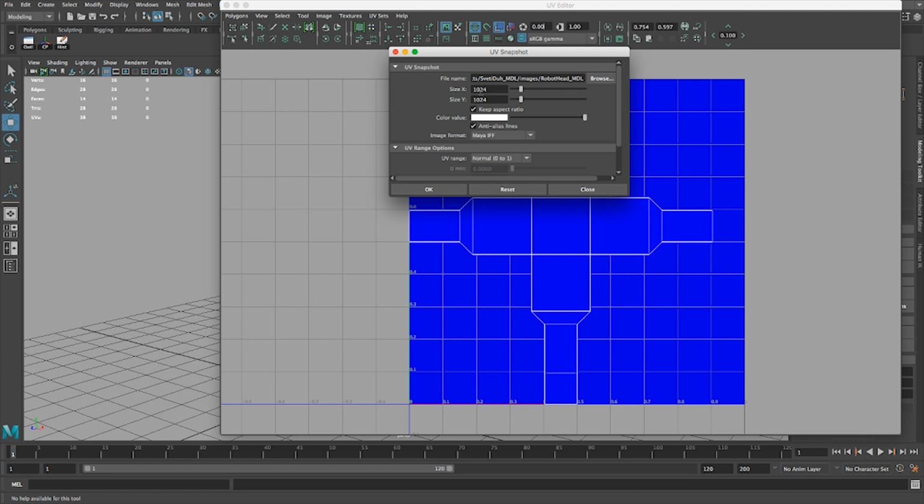Even if I'm going for render or for an engine, I would still do it in bigger resolution, and then scale. It's always easy for me in Photoshop to have a texture which is 2K, and then save it as 512 if I want to save memory. I cannot do the opposite. If I painted my texture in very low resolution, that's what I have. So I rather always have a bigger resolution, but for our sense, let's change this 1024 to 2048. This 2048 means a 2K texture.